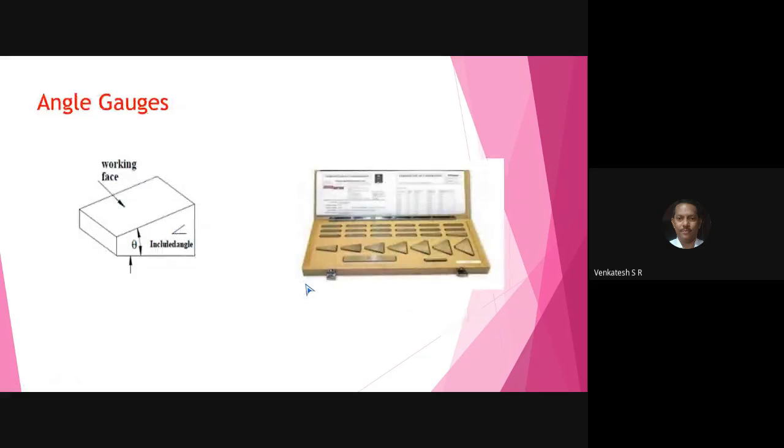And next, come to the point. All of you have already discussed the slip gauges. In the same way, angle gauges are also available. All of you observe here the shape and size, and different sizes are available. This is the working surface, this is the included angle, and this is the theta. Different angle pieces are available here. Use the different pieces for measurement of angle.